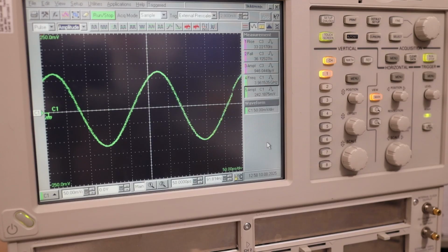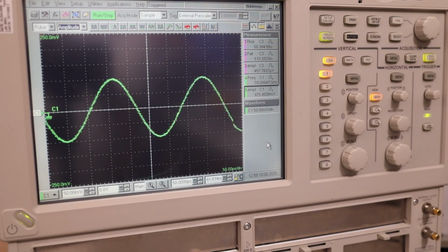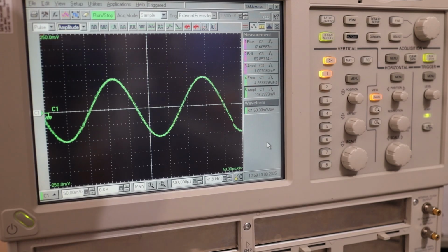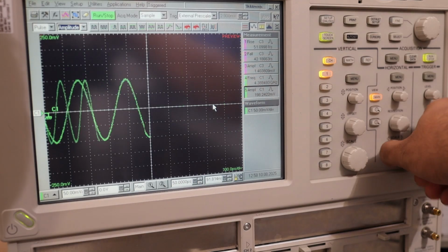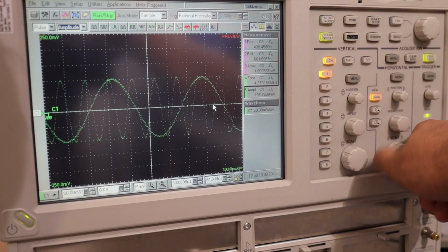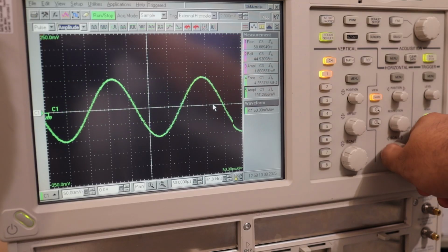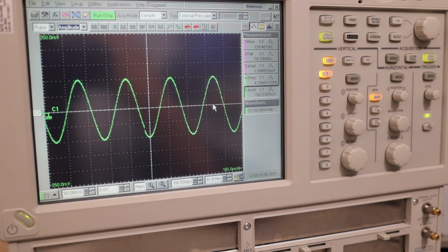Now I set it to the maximum, 4.4 gigahertz, and do you see a 4.4 gigahertz signal? Yes, we see exactly a 4.4 gigahertz signal. Measurement amplitude is around 200 millivolts per division. Around 200 millivolts signal amplitude. It works reliably well at 4.4 gigahertz. The oscilloscope has verified it. Works pretty well.